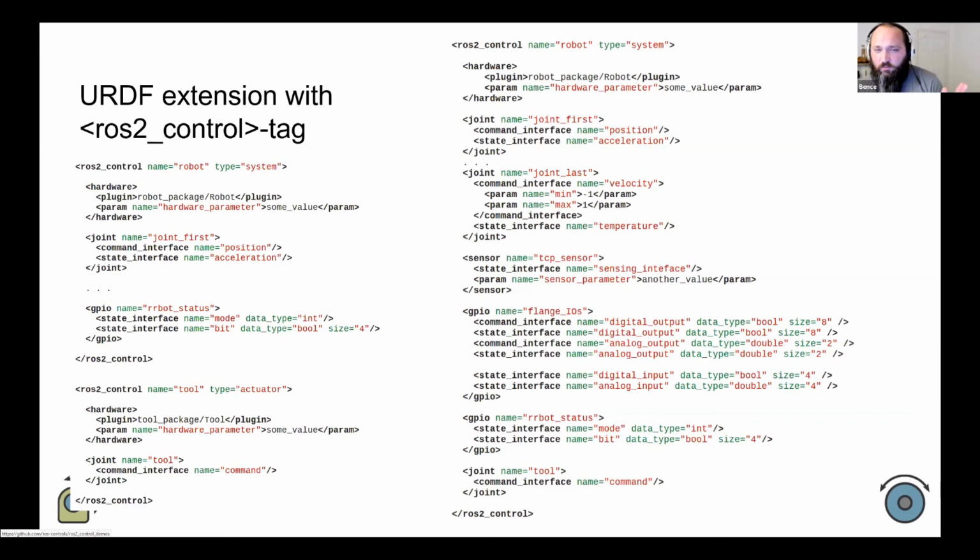I may be wrong, but the way I see micro-ROS is this: I'm not sure if you're familiar with ROS serial, where you would pre-compile with the ROS message toolchain and all that stuff. You could recompile the standard ROS messages for any embedded platform, and you could more or less make a native application on your microcontroller that uses ROS.